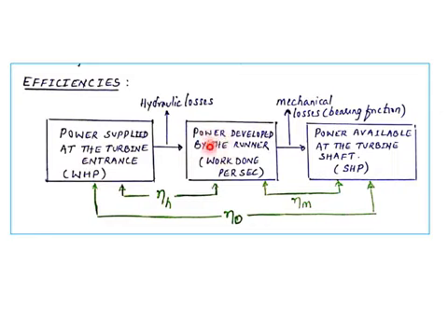Therefore work is done on the turbine. That is what is known as the power developed by the runner. So it is work done per second. This work done per second is utilized in running the electrical generator. Whatever power is available at the shaft is the output. When you are supplying power to the turbine runner, work is done here. So this is output and this will be input. Output is always less than the input, therefore there is a loss taking place, known as hydraulic loss.